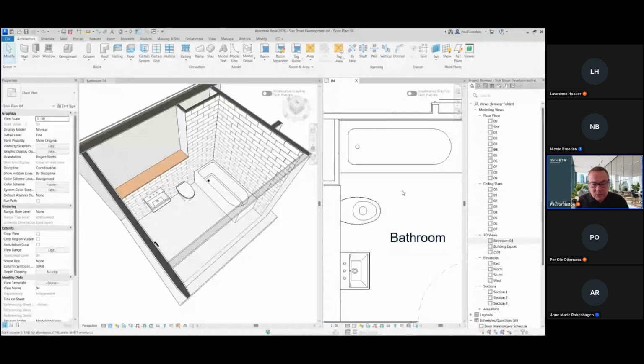I've also tested it with linked walls. So if you link your model in, you need to create the room in the live model, but you can have the linked model as wall bound in. Then this functionality also works with the segments as well. So there's a nice bit of help there for when we're working with linked files.